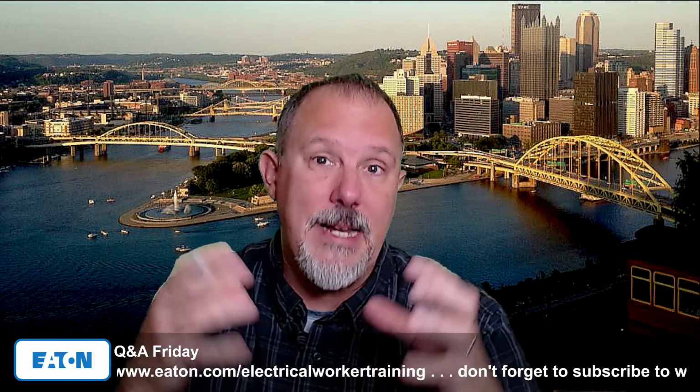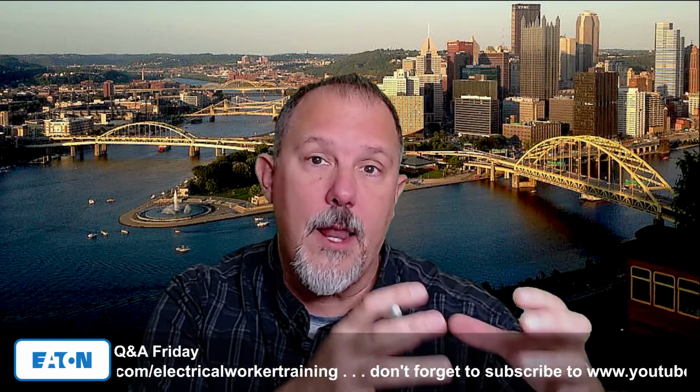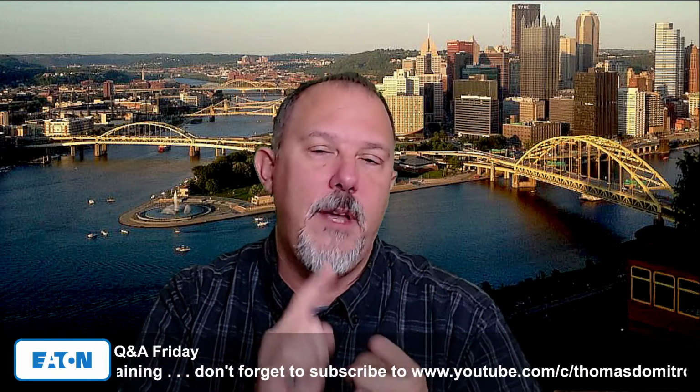All right, very standard practice. Assume there is never a termination spec. How many conductors in the same terminal? Very standard practice: assume one and only one. If you look at some equipment, especially breakers, some breakers will tell you that you can put multiple conductors. Some terminals, like power distribution blocks, will tell you here's how many conductors you can put under one lug. But it will also tell you that, for example, you may not be able to put a solid conductor and a finely stranded conductor or a stranded conductor under the same lug.